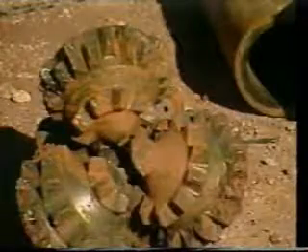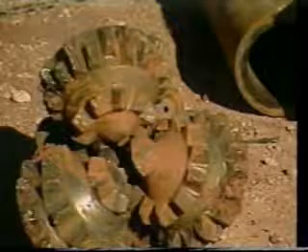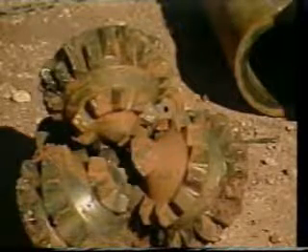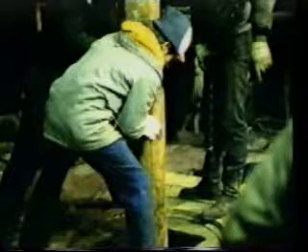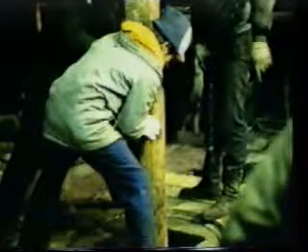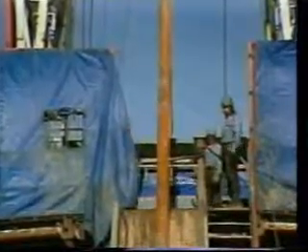Our drilling program has been designed so that the initial bit will drill a hole large enough for casing that can accommodate successively smaller bits and casing strings. The number of casing strings required to safely reach our target depth will determine the initial hole size. Attached to the first large bit are the first drill collars.